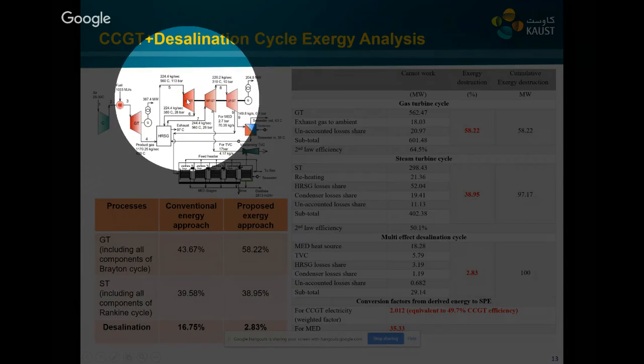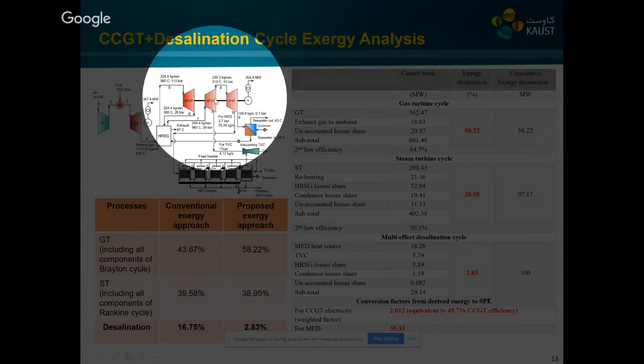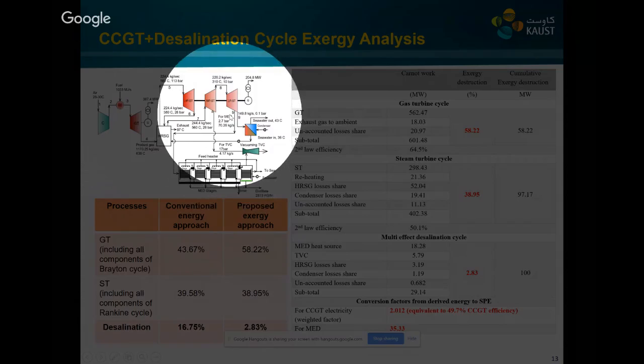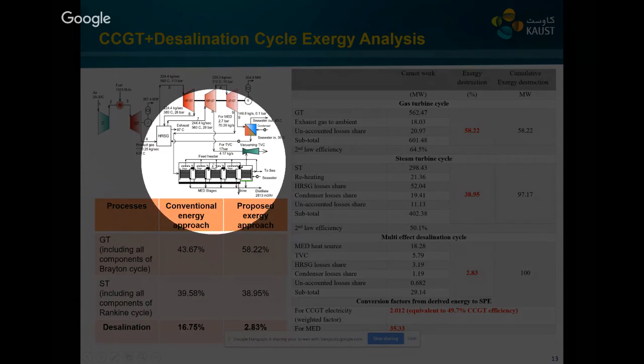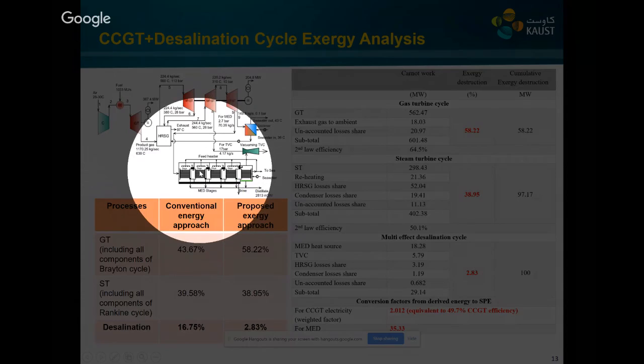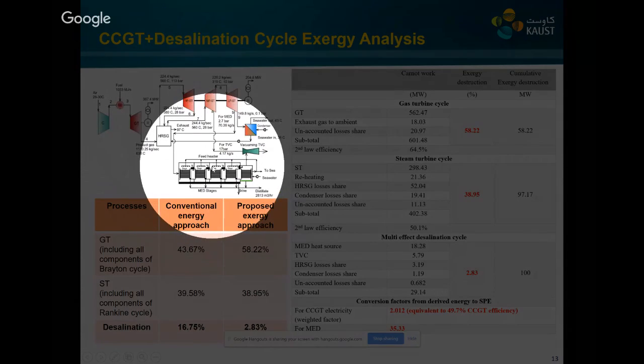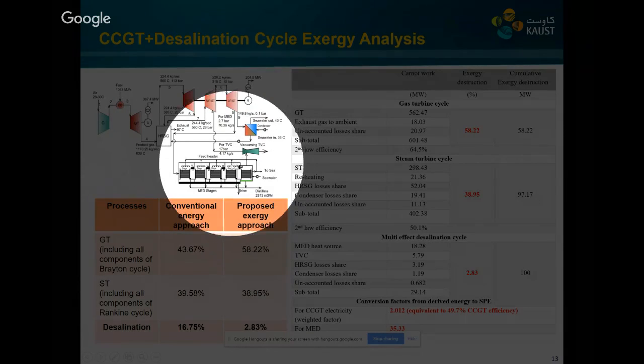It can be a three-stage steam turbine: high pressure, medium pressure, and low pressure. It can be a one-stage steam turbine depending upon the power requirement. If it is a thermal desalination system, normally the steam is bled from the last stages of the low pressure turbine, and then supplied to the thermal desalination system. If it's the RO system, then the RO system doesn't have synergy with the CCGT power plant, because it does not need to be with a power plant, as it utilizes electricity directly from the grid.